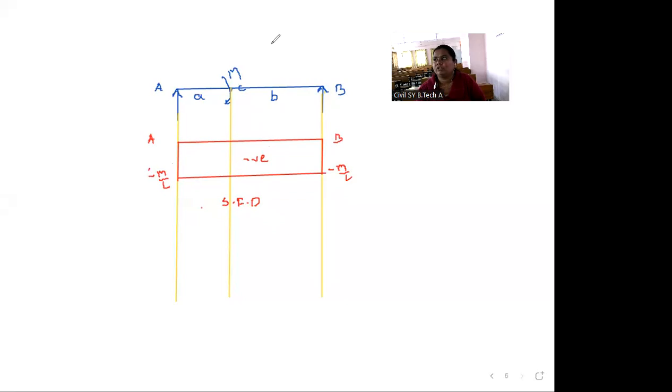After that we will draw the bending moment diagram. For drawing this, first we draw the baseline. Here, X is raised to power 1, so our connection between two points is an inclined straight line. The bending moment at point A is 0, the bending moment at point B is 0, and the bending moment at C.